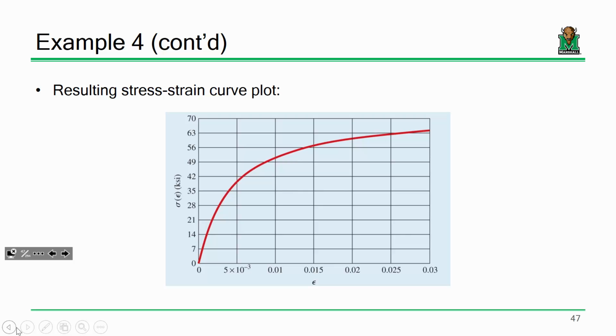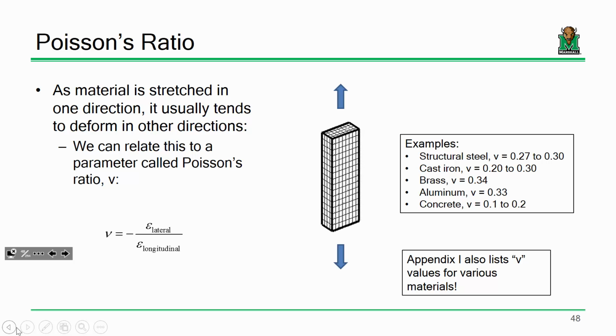I want to introduce you to some other material-related aspects, some secondary stuff that we haven't quite talked about yet, but that is very important. So one of those is what's called the Poisson's effect. This probably makes sense if you think about it. Go back to that concept of the rubber band. Take the rubber band and stretch it. It gets longer, but if you use your noggin and think about it a little bit, it doesn't just get longer, it gets thinner, right? Make sense? Well, that's called the Poisson's effect, the idea that as you elongate something, it gets thinner, okay?